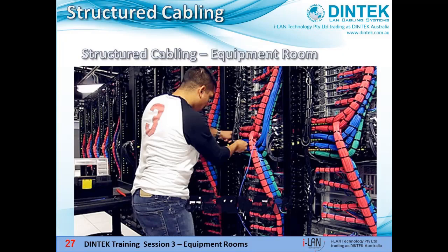If any of those cables ever have to be replaced or new ones added in, you've got a huge pain on your hands. Unless you've got someone being paid by the hour to do it, what will happen is people will come along needing to do an add or move or an emergency repair. They won't have the time or the inclination to cut off and redo dozens of cable ties, so sooner or later it'll turn into a big mess.